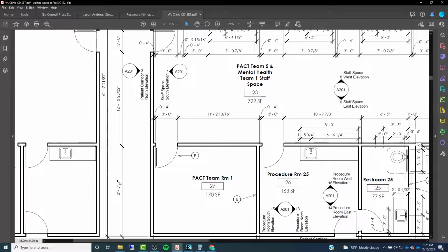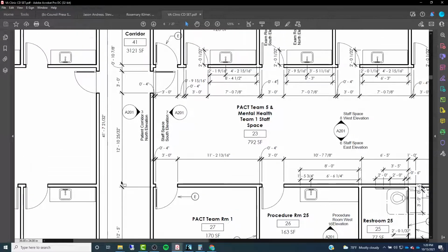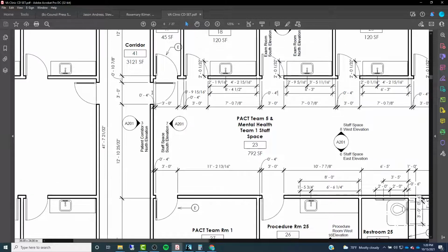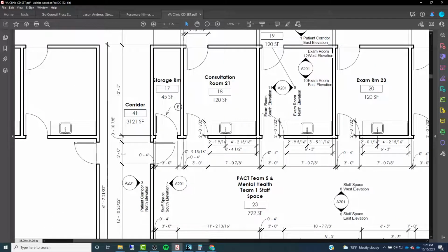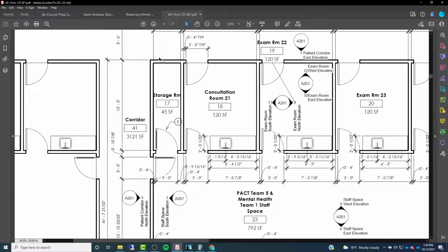So there's our 12 foot 5 inch dimension. Then we're going to keep the string going by going to this door opening. In this case, because the door tags were not used, we actually indicated how big that door opening was. Then we're going up and ending at this corner. But usually it's going to be consistently on a particular face of the wall.